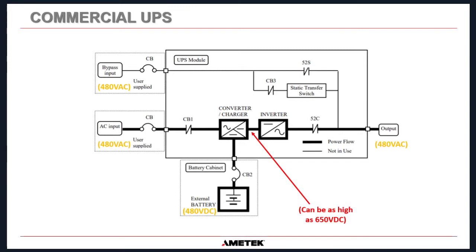Okay. And you can see on the bottom there that for a commercial style UPS, the battery is near enough always 240 cells of lead acid cells. They are 2 volts nominal. So the nominal voltage for a commercial UPS battery is usually 480 volts. Now, if any of you are interested in the NFPA guidelines for arc flash PPE, that pretty much takes you into arc flash category 3 PPE to work on this battery here. So bear that in mind when you are designing a UPS, that the bus voltage of the battery can affect how maintenance is performed in the field.